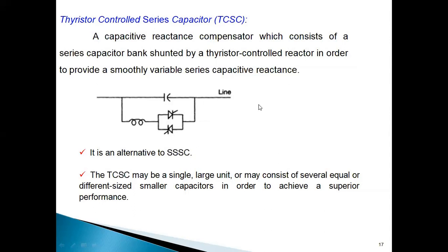Okay, fine. We have a TCR, that is a thyristor controlled reactor. This portion, I want to encircle this. And we have a series capacitor. Here the concept is that in series compensation, we are trying to reduce the reactive impedance. We need to cancel a portion of the series inductive reactance, so XL will be compensated with XC. The formula for the impedance of the transmission line is Z equals R plus j(XL minus XC), or if I ignore R, it is only j(XL minus XC).